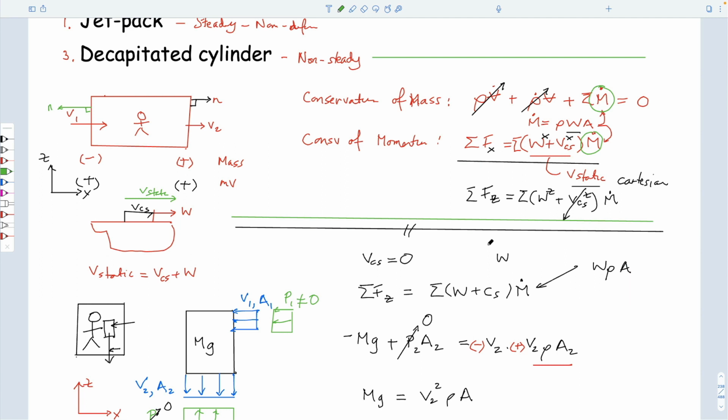And you can probably get a feel for these, because the basic lesson of what we talked about on Wednesday was you have two conditions. You either hold the vane static and impinge fluid on it. That gives you the maximum reaction force because the velocity of the control surface is zero, and therefore the product of this mass rate and this flow rate is maximum. Or the velocity of the control surface has to exactly equal the velocity of the impinging fluid, in which case there's no force applied on the vane, because these cancelling each other out is the only way that this term can be zero.